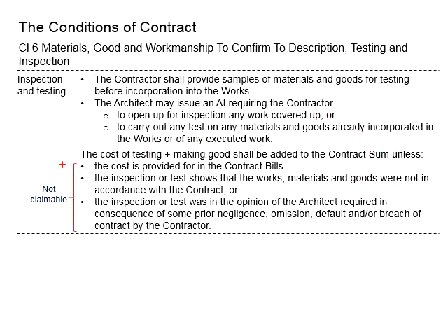What you see here are the principles for the contractor to be entitled to claim the cost for the testing and making good when the things have already been incorporated in the work. It is very much dependent on the quality of the work as given by the contractor. If the quality is okay, it is claimable, but you will need to check whether the cost has already been counted in the contract bills. If it is already counted, then it will not be subject to change in terms of the contract sum. If it is not counted, it is valid for the contractor to claim for the cost.